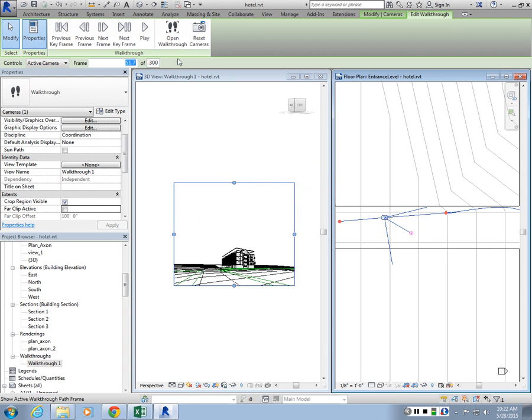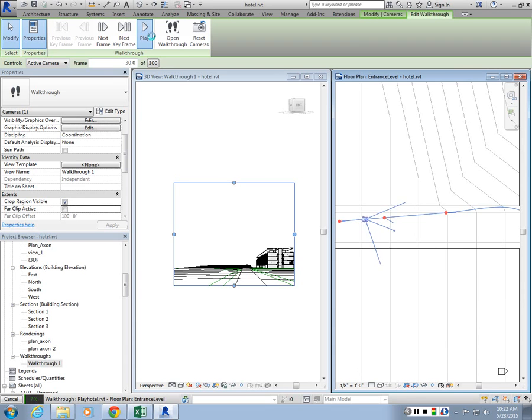So now if I go to 0, or the first frame, the target is here. But if you look at this keyframe now, the one that I just edited, the target is going to face this direction, right? So it's showing it to me with a light blue arrow. And if I press play, it's going to interpolate to that and then go back to being aligned with the path, right? So this way you can customize what you want to see, which direction you want to look at specific keyframes.